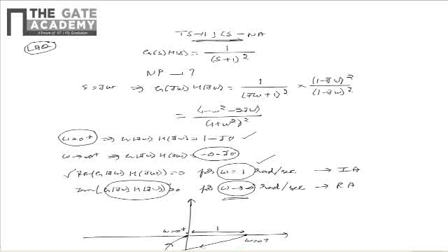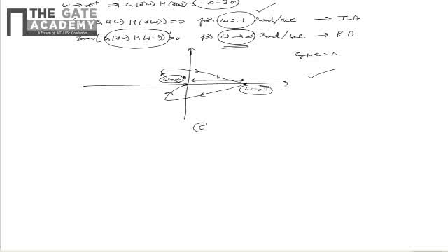And also we know that the plot as ω is varied from infinity- to 0- is symmetric with the plot corresponding to ω = 0+ to infinity+. And also we know that the type of the system is 0. From this we can say that the number of encirclements of the Nyquist plot around the origin is 0. From this we can say that the Nyquist plot of the control system can be obtained as shown. Hence the correct option which corresponds to the Nyquist plot of the given control system is C.